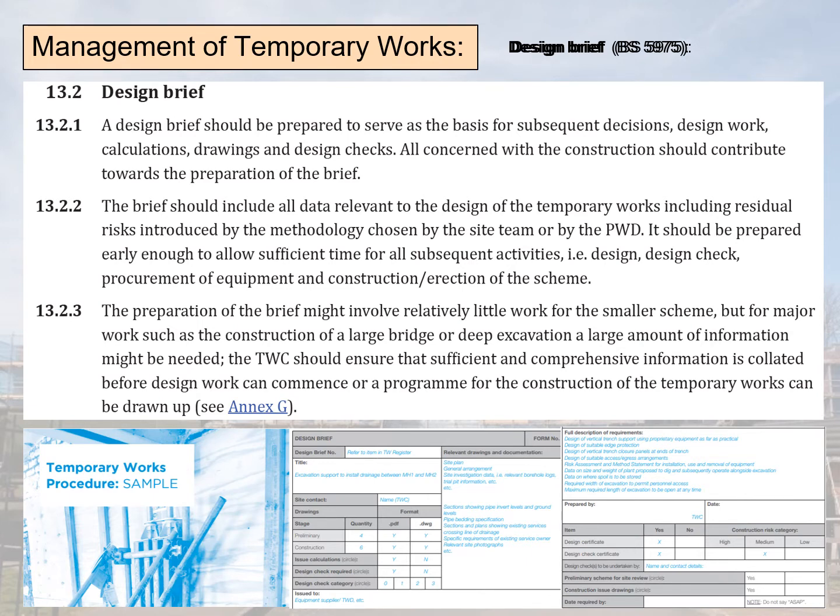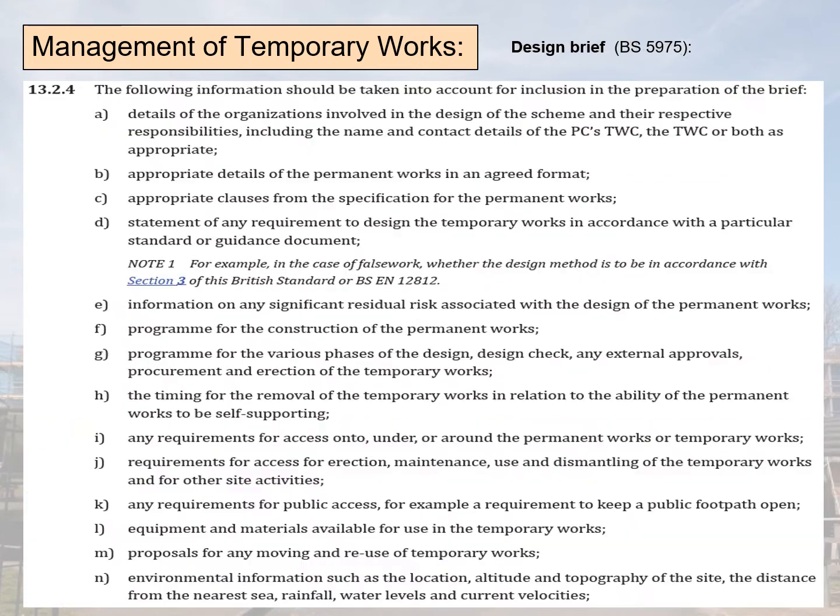The design brief should include all data relevant to the design of the temporary works, including residual risks introduced by the methodology chosen by the site team or by the permanent works designer. These should be prepared early enough to allow sufficient time for all sequential activities: initial design plus challenges, design checks, procurement of equipment and construction erection of the temporary works scheme. It should also allow prior training to be implemented.